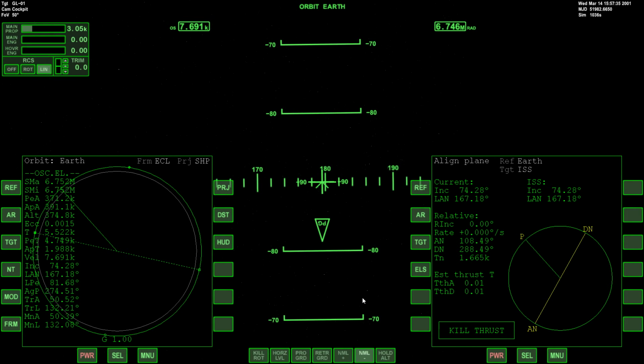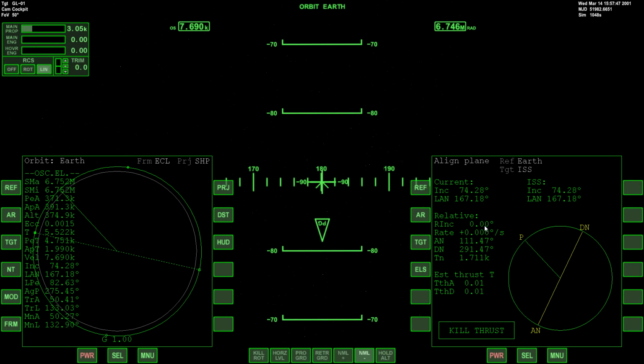I should, however, mention that if you have the non-spherical gravity sources enabled, your orbit will be perturbed somewhat from that. So you'll notice that relative inclination just won't stay right on 0, but it should never go above 1 degree. As long as you're under 1 degree, the synchronized MFD will work, and I'll go into detail about that in the next part. But just keep that in mind. If you notice that it's not staying right on 0, don't worry about that. It's probably that non-spherical gravity setting being enabled.